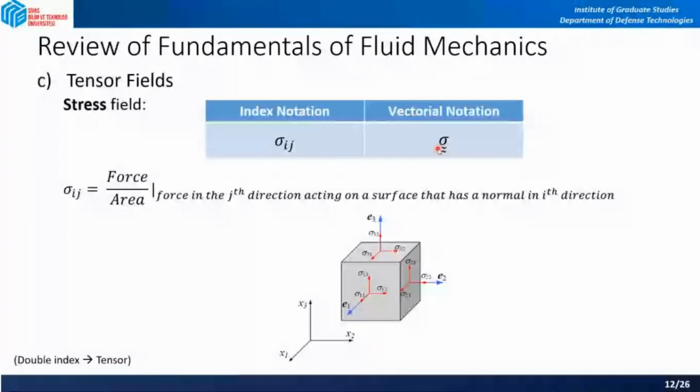So in order to describe second order tensors like stress, if you consider a scalar with one value and a vector with three values, then a second order stress normally needs nine numerical values at a point in space. And you remember, if there are certain conditions like a symmetric tensor, then you would only need six values inside the tensor. So one value to describe the tensor does not make any sense.